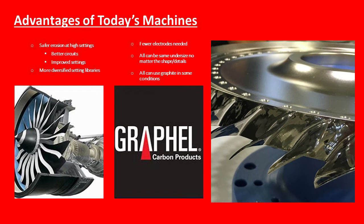Fewer electrodes are needed because of this. Because of the orbiting capabilities, you make all the electrodes the same undersize. That makes it easier for the machining of the electrodes themselves. And then, of course, all the machines today can use graphite. They can all use copper. They can all use copper tungsten. They have settings for all of this.